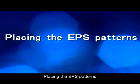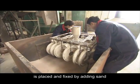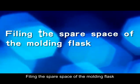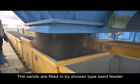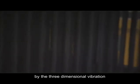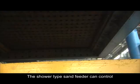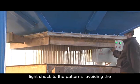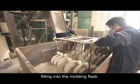Placing the EPS patterns. After being compacted, the cluster of EPS patterns is placed and fixed by adding sand, filling the spare space of the molding flask. The sands are filled in by a shower type sand feeder. The sands occupy all the space of patterns by the three-dimensional vibration, and the bulk density will increase. The shower type sand feeder can control the sand feeding automatically, which is featured with uniform and quick sand feeding and light shock to the patterns, avoiding the deformation of the patterns as the sands are filling into the molding flask.